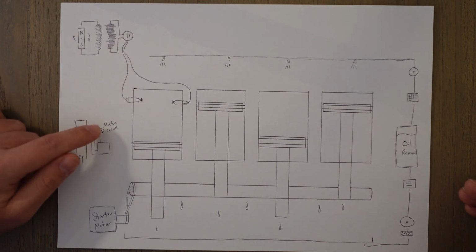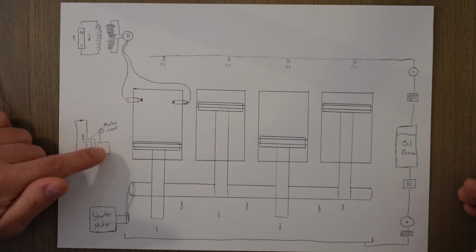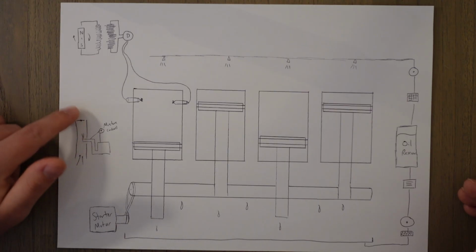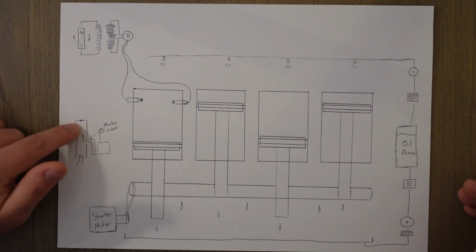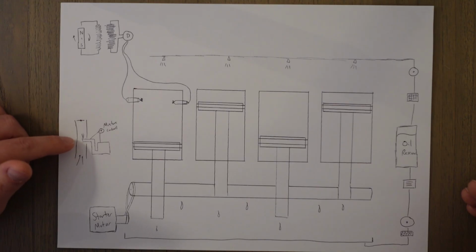We also have a mixture control valve, which will basically control the ambient pressure in the little fuel reservoir and the U-bend, and if we create a higher pressure here, then more fuel is sucked up, and if it's a lower pressure here, less fuel is sucked up by the Venturi tube and that Bernoulli's theory that we talked about.